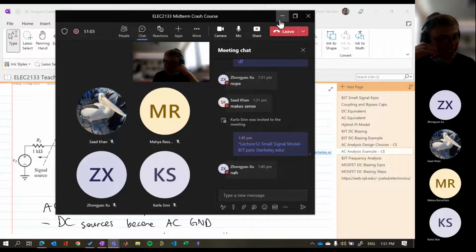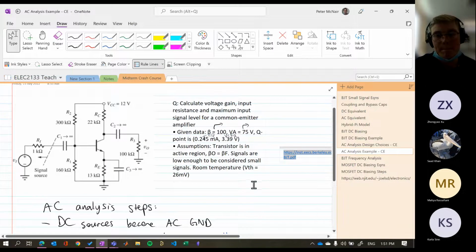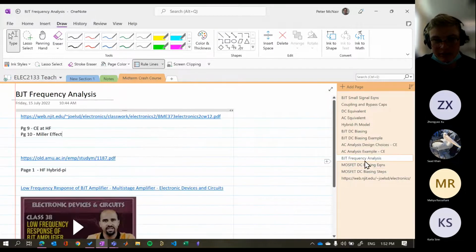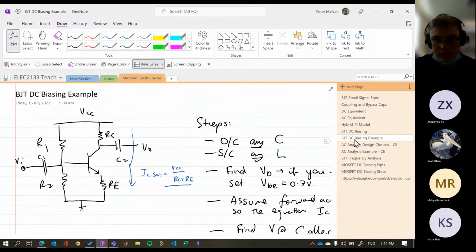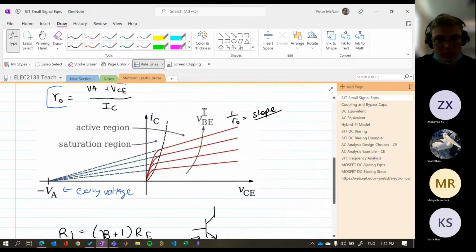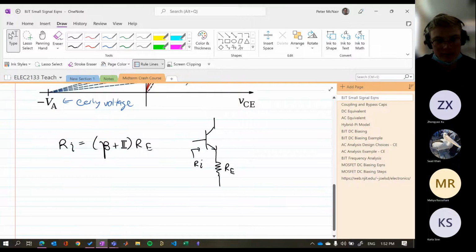It's definitely a lot of redrawing and getting things looking neat, and there are a few little hacks here and there, mostly to find the Thevenin resistances. And I guess the main one that I think of, which I'm going to keep coming back to, is that when we're reflecting resistances between base and emitter, we can use this factor of beta plus 1.